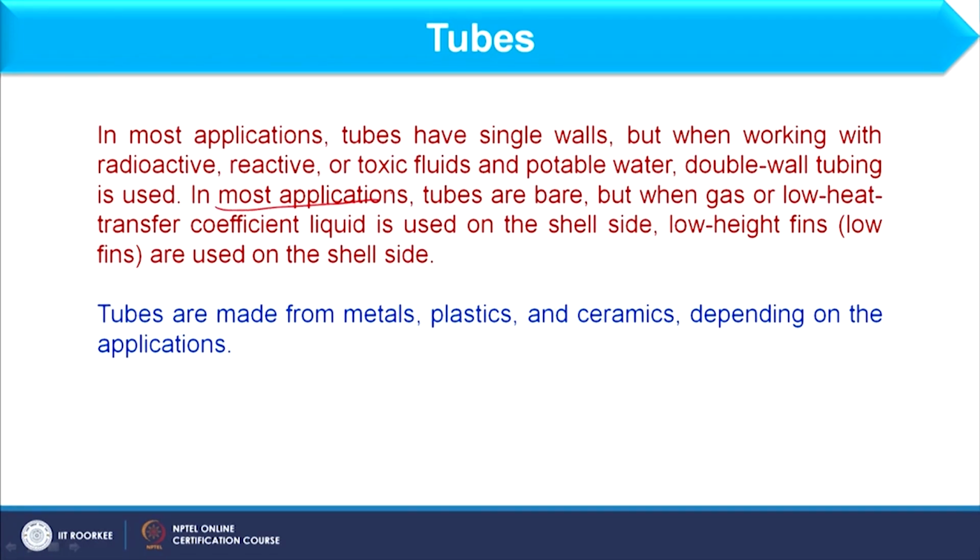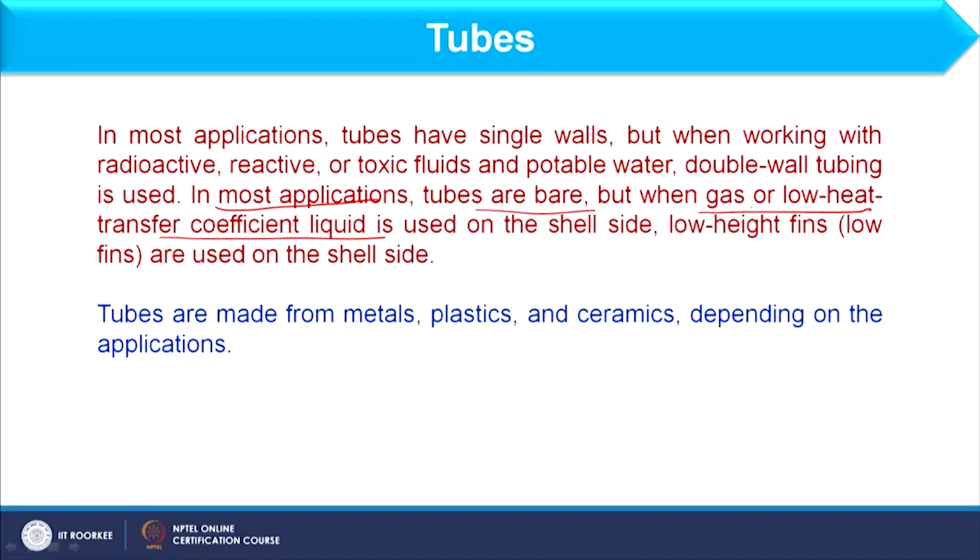And in most of the applications tubes are bare, it means we use tubes as they are, which do not have any other design over them. However, in some applications like extended surfaces, when we are dealing with gas or low heat transfer coefficient liquid on the shell side, we should use low height fins, which are basically attached over the tube. So, these are basically tubes with fins, okay.